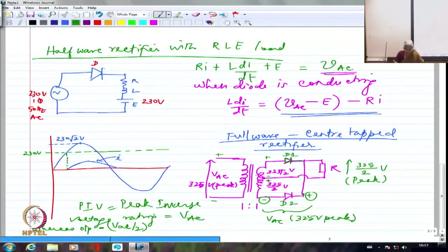as the output. If there had been two diodes conducting like a bridge, which we will see eventually, we are invariably going to see that 1.4 volts are dropped, 0.7 plus 0.7. When you are talking about 5 volts power supply or 3.3 volts power supply, this 1.4 volts matters so much, because out of 3.3, if 1.4 is going away, then I get very minimal output voltage. Or correspondingly, I have to design the transformer secondary for a higher voltage.